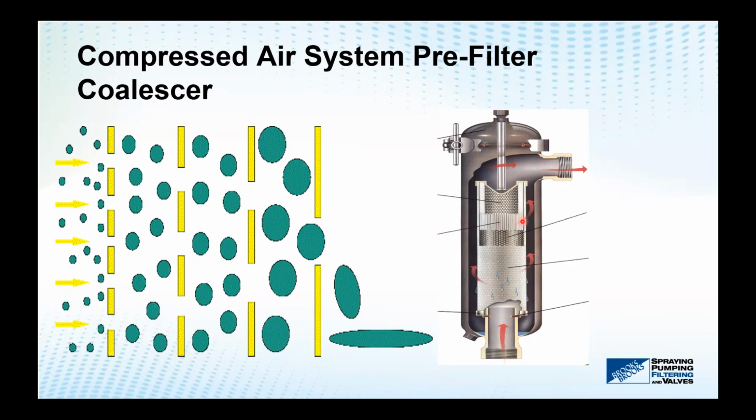Hey Russ, that's a good point, because it makes me think the better we can filter the air prior to the compressor, if you have the proper metallurgy, and you don't have acid coming in that's corroding your vessels or causing damage to the compressor, then in theory these filters should have an infinite life because, like you stated, their goal is to remove liquids. In theory there should be a minimal amount of particulate, but in reality we always get something in there. And yes.